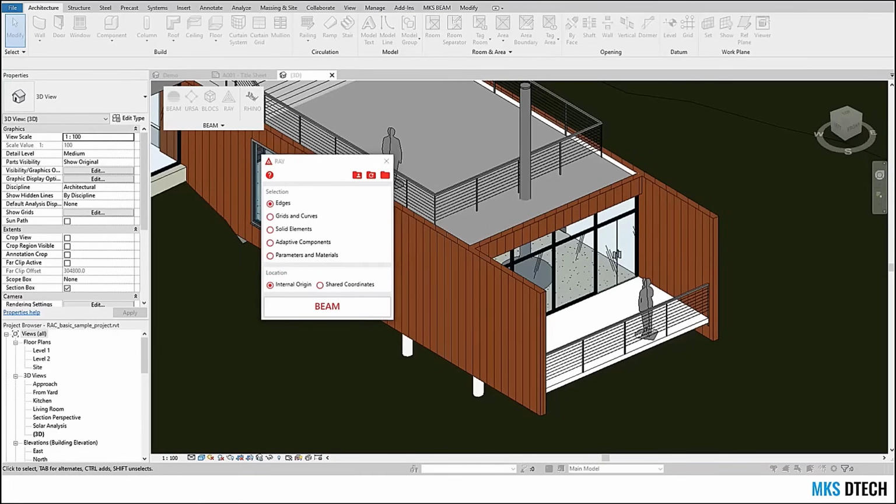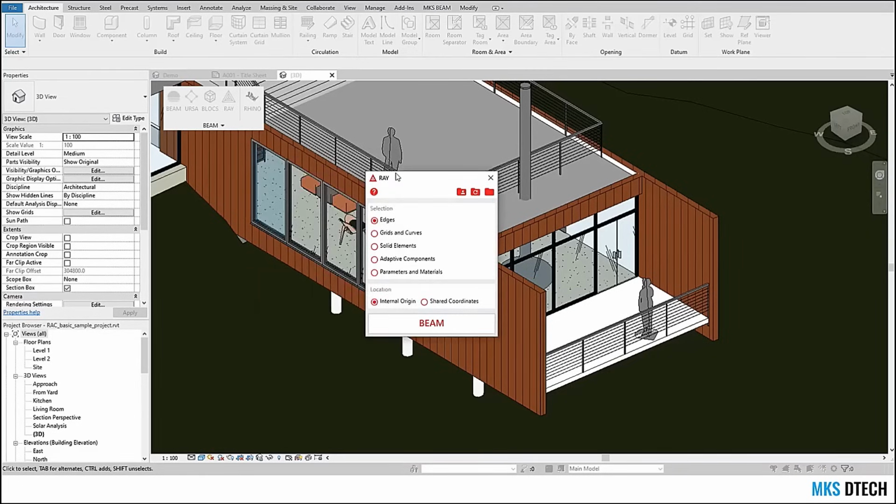Also, if you have Rhino Inside Revit installed, there might be some conflict, because Rhino Inside Revit and BEAM both use Rhino Inside technology, and only one Rhino can run inside your Revit application. So, after discussing with Mikael, we give priority to Rhino Inside Revit to launch Rhino.